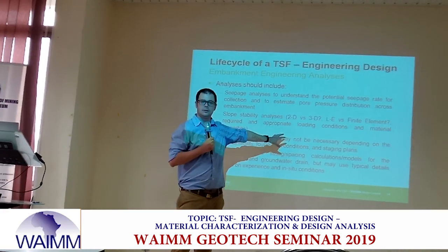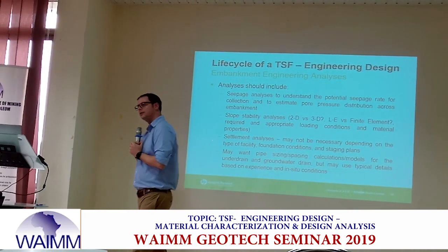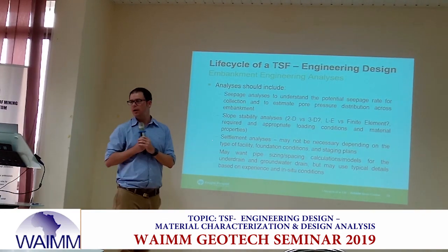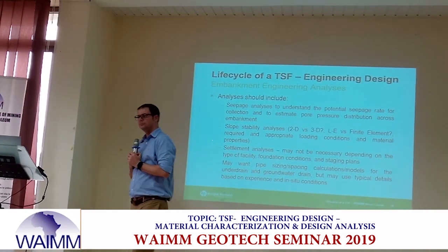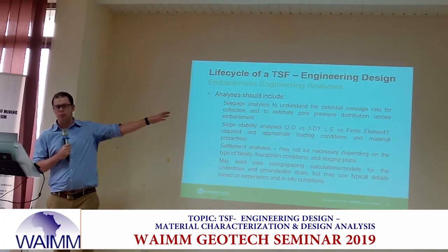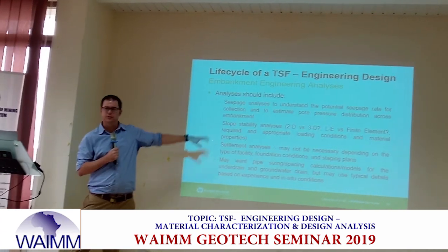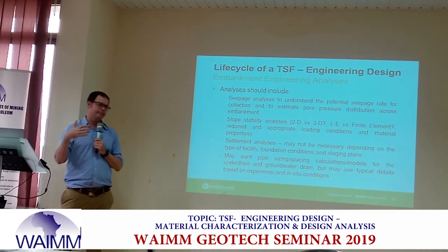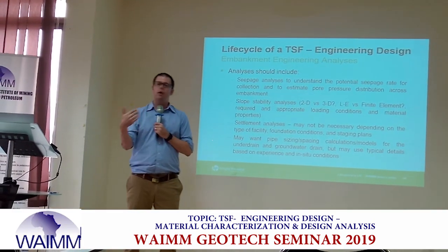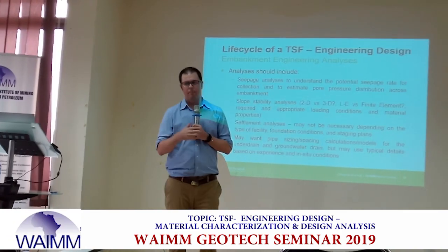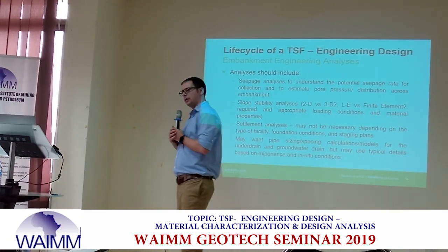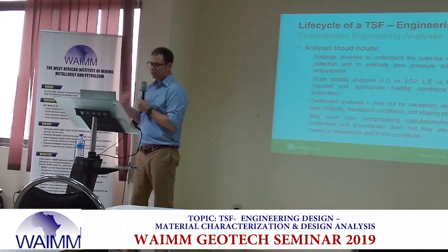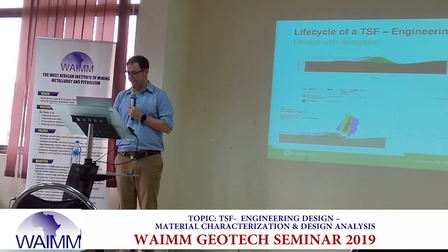If I design something that has to be a half-meter wide, it can be a meter wide. It can be 1.1, a standard bucket width. So that's why we sometimes don't rely too much on analyses when we do some of those types of calculations. Similarly, in an embankment, we might show that our drainage might only need to be 1 meter thick. But placing 1 meter of material in thickness on an embankment is sometimes very challenging because of the slopes and because of the size of the equipment. So we might make some modifications.